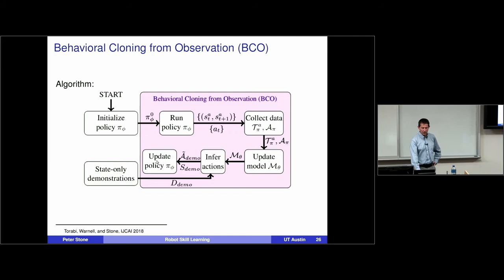Yeah. So we're going to use a neural network method, a learning method that's given training data and learns the best function within its policy class. The robot, as it's collecting its data, just gets state, next state, action triples, and it tries to learn using a conventional machine learning method, minimizing the loss in the prediction on a holdout set. It's not necessarily going to get the right actions, or the only actions, but it's going to get a generalization based on the training data. So it's a learning-based method.